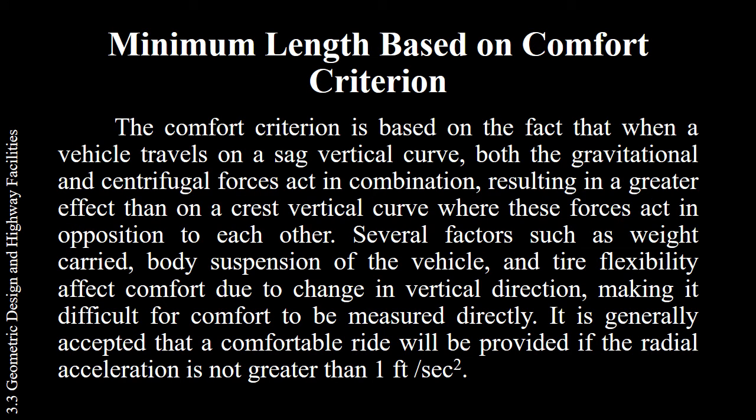Minimum length based on a comfort criterion. The comfort criterion is based on the fact that when a vehicle travels on a sag vertical curve, both the gravitational and centrifugal forces act in combination, resulting in a greater effect than on a crest vertical curve, where these forces act in opposition to each other.